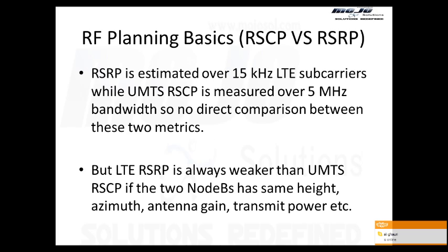So the pilot channel for UMTS is typically, not exactly, 10%, which usually comes to 33 dBm for a 40 watt radio, because most of the deployments are 40 watt, which I guess is 43 dBm. So you will find it at 33 dBm. For LTE, if it's a 40 watt radio, you will still see the power is not 10%, it's less than 10%, and usually it comes to about 23 dBm or 22.5 dBm.